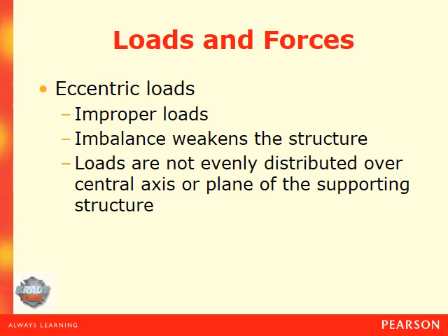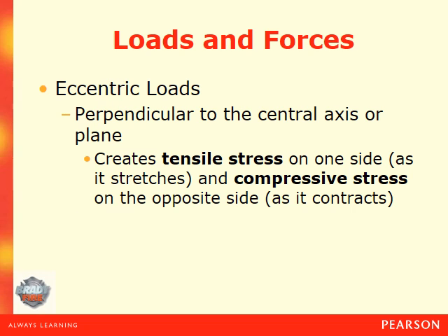Now we have an eccentric load, and that's an improper load. It's an imbalance that weakens the structure. Loads are not evenly distributed over the central axis or plane of the supporting structure. So this is something that's kind of off-center. Eccentric loads are perpendicular to the central axis or plane. It creates tensile stress on the side as it stretches and compressive stress on the opposite side as it contracts.